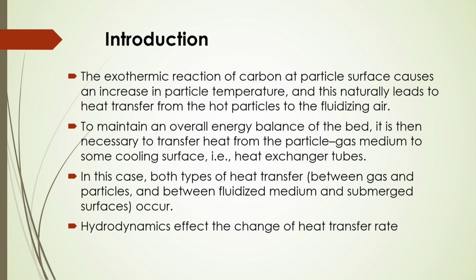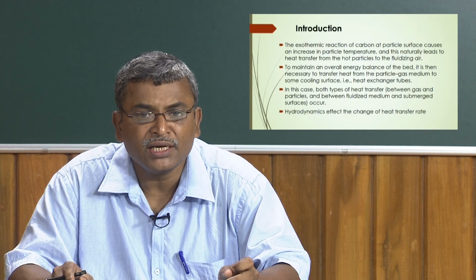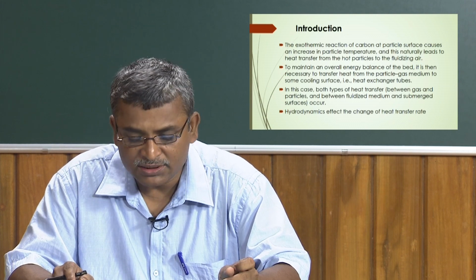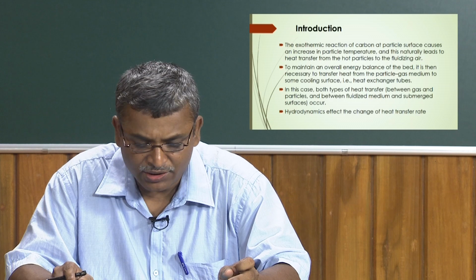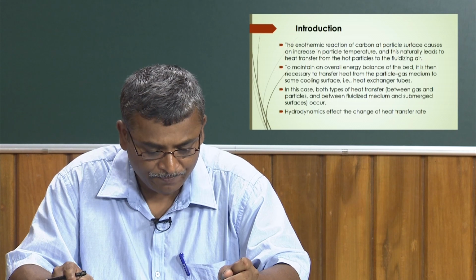Now, where will this heat transfer characteristics be important? Because we are going to study these characteristics, this knowledge should be utilized somewhere. So, the heat transfer characteristics are important in this fluidization operation. Now, you know that exothermic reaction of carbon at the particle surface causes an increase in particle temperature, and this necessarily leads to heat transfer from the hot particles to the fluidizing gas.